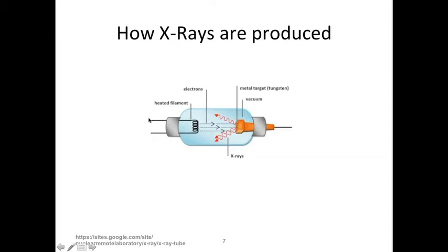So basically, this is one X-ray generator. You can consider that it's kind of a bulb, where you heat up a filament. It's a metal filament, and then you apply a very high potential between this filament and this, your target. Because this is the electron source, you apply a negative terminal here and positive on the other side, so you can push electrons to the other side. There is an air gap, so it's a vacuum.